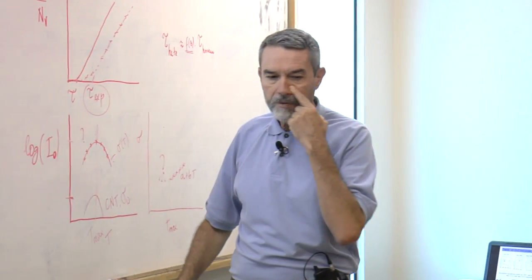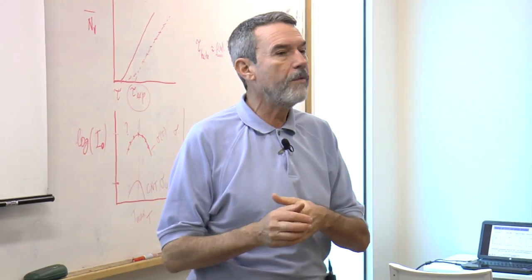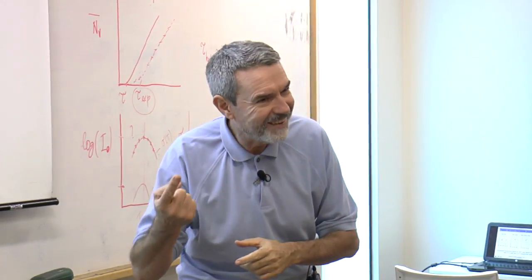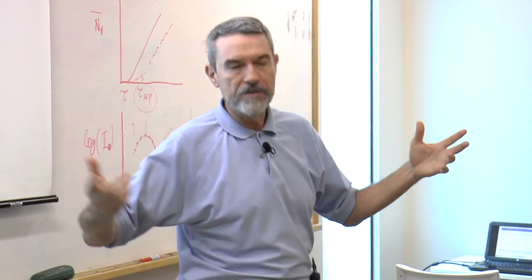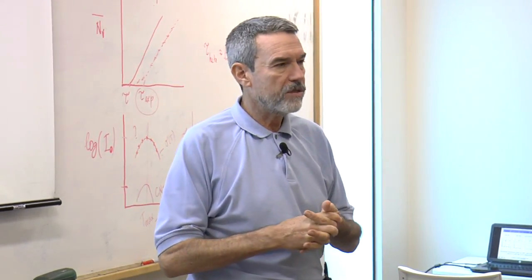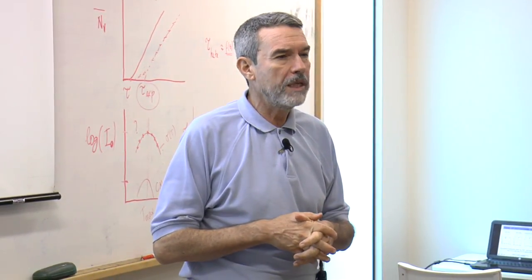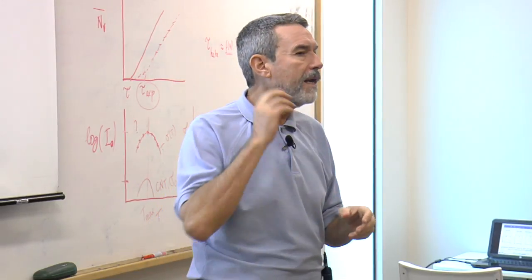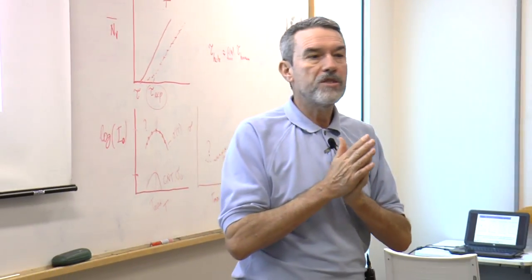The glass will relax, or the liquid, because we are above Tg, the supercooled liquid, will relax much faster than nucleation even starts. We have calculated these for several systems. And also this is true below Tmax. And that's why the stresses do not play a role.